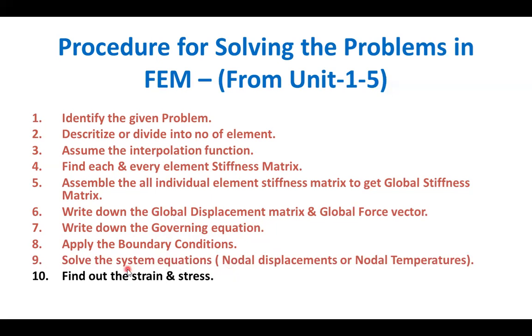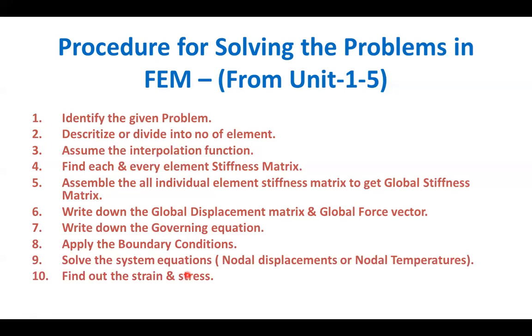After getting the nodal parameters, that is, the displacements, you should focus on how to calculate the strain for the elements. So you should find out the strains. Then after finding the strain, by using Hooke's law, you calculate the stresses also. These are the very important steps that are common for all types of analysis.